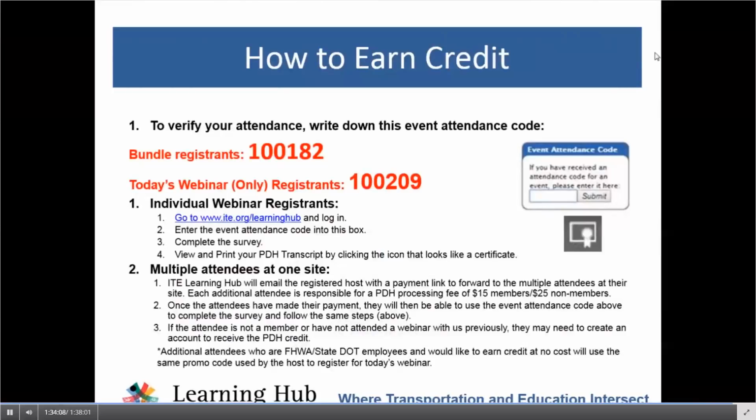And while I know level of service is tied to policy in a lot of locations, really ICE is one way to overcome some of those, frankly, sometimes outdated ways of looking at things, to really not only look at the peak 15-minute level of service, which is really what we're talking about when we say HCM, but moving beyond that to look at whole day performance, life cycle cost, safety impacts, user impacts, quality of service measures, where really the operational performance as predicted in the HCM becomes one of many performance metrics that are part of an ICE evaluation.